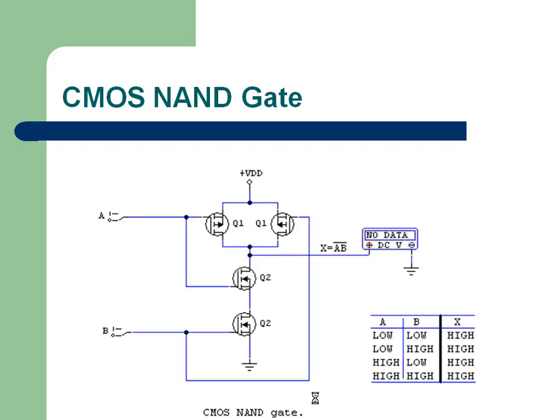You have inputs fed here, optional. Maybe in some logic family there may not be inputs here, there will be only inputs here. In some logic family like CMOS, inputs will be both here and here. So how we design our logic is, pull down network is something which will pull down this node to ground. Means if pull down network is on, output is 0. If pull up network is on, output is 1.